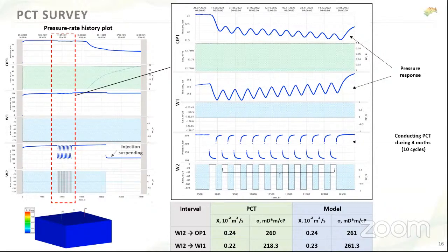Actually, that's the limitation of standard pressure interference, and the reason why it isn't used widely, despite it was first tested more than 60 years ago. And if we do pulse code testing instead of standard pressure interference, we avoid such a problem with production deferment.